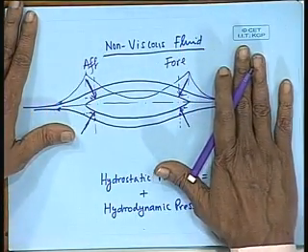Again, assuming no viscosity, no disturbance to flow in any other manner like separation, assuming the entire flow is streamlined, these forces will equal aft forces. That means, the total opposing forces on the fore body will be equal to total supporting forces of the aft body. Therefore, the resultant force in the longitudinal direction will be 0.